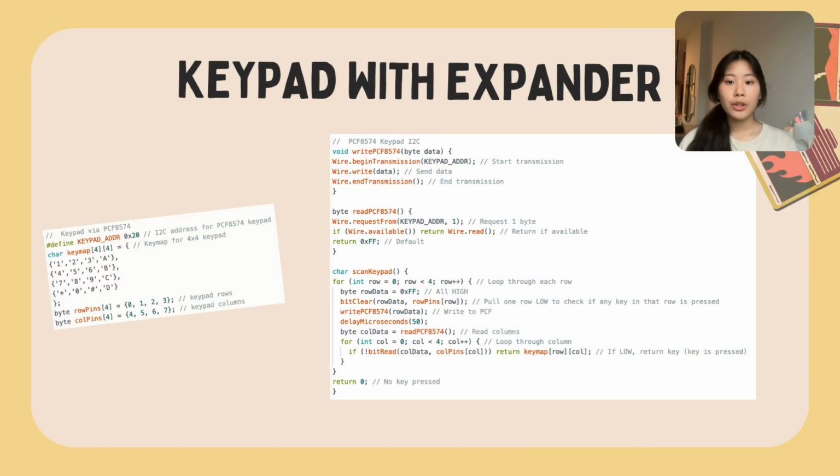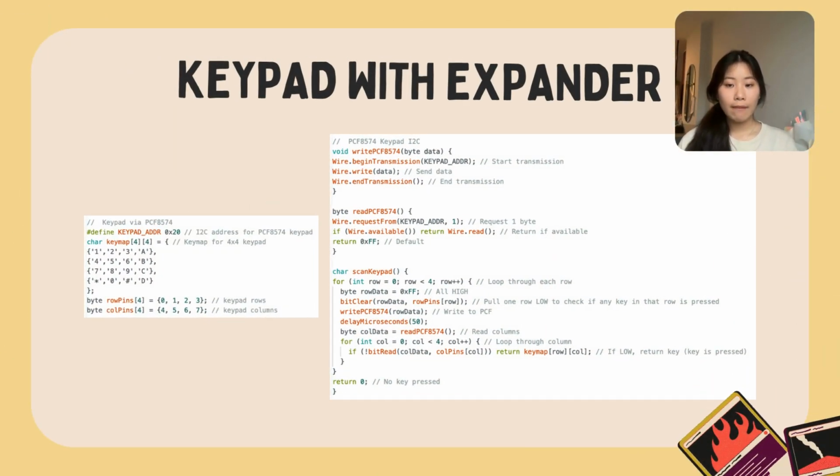For this part, we control the 4x4 keypad using a PCF8574 I2C expander. The key map defines what each key does. The write PCF8574 and read PCF8574 functions handle communication with the keypad via I2C at address 0x02. In the scan keypad function, each row is pulled low one at a time and the columns are read. If the button connects a low row to a column, it means the key is pressed. The function returns the matching key based on the key map. This method saves Arduino pins while still reading all 16 keys.